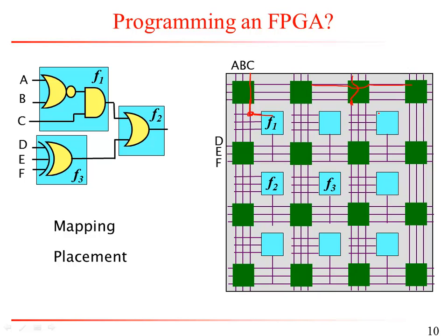And there are programmable switches that, for example, say this connects to this one, this connects to that one. So you must have some sort of flexibility in these intersections, in what are called the switch boxes in the FPGA. Same thing happens with the functional unit. This line is electrically disconnected from these three lines, and you would program a switch to make a connection. This is basically a pass transistor that says this input of the function comes from this wire segment, which in turn could be coming from this pin or somewhere else, right? So the circles show that this is a programmable switch that we program to be on, to connect the two wire segments that connect to it.